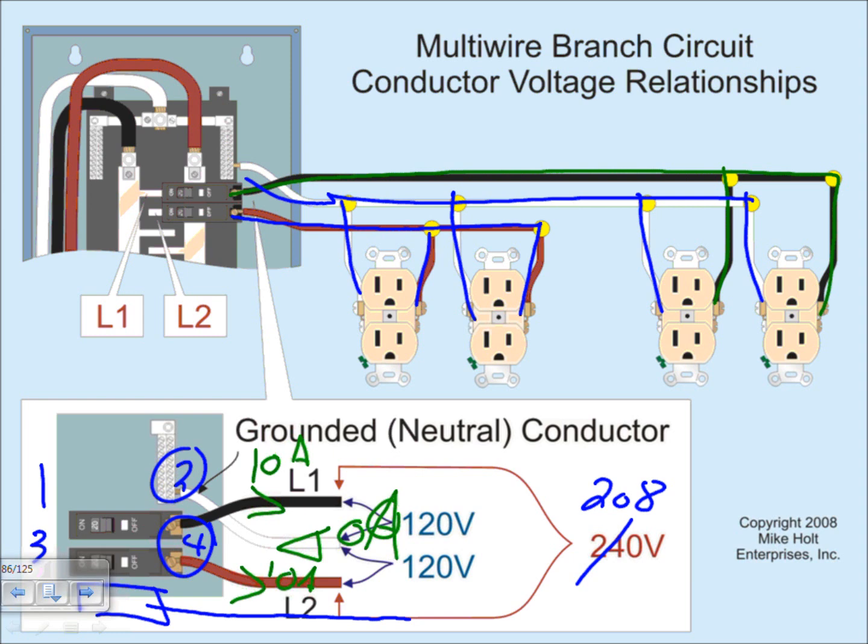The power has reached the destination. So you have 10 amps here, I have 10 amps here, and what's going to come back right here is 0 amps. Why? Because by design, these currents are going in opposite directions. They neutralize each other as they reach the destination back at this point.